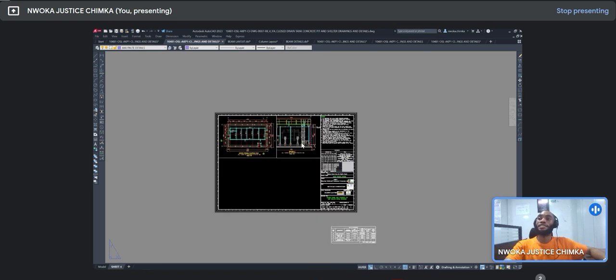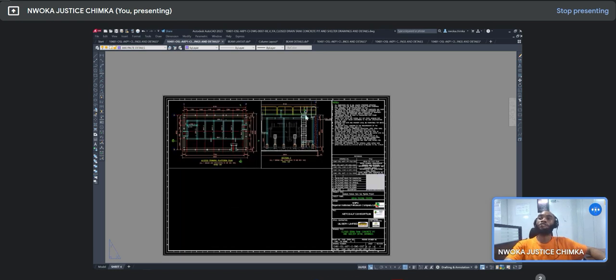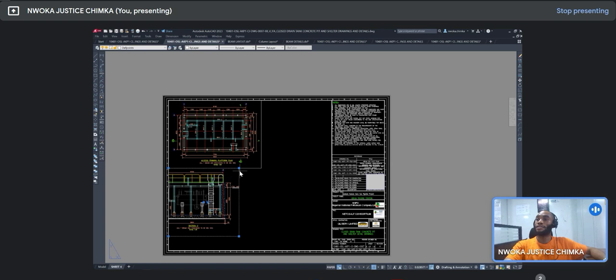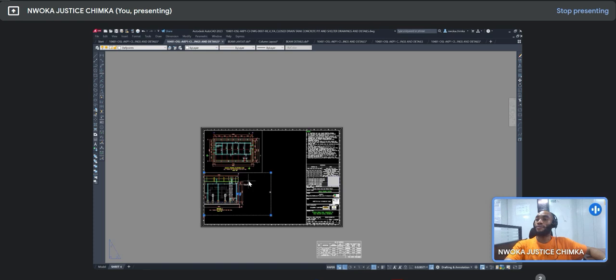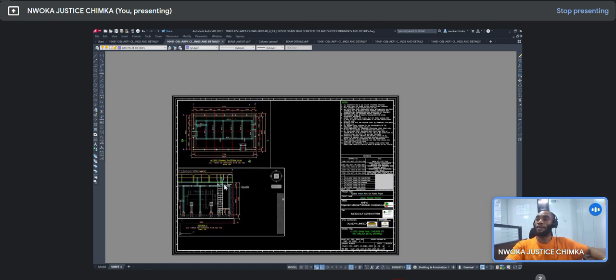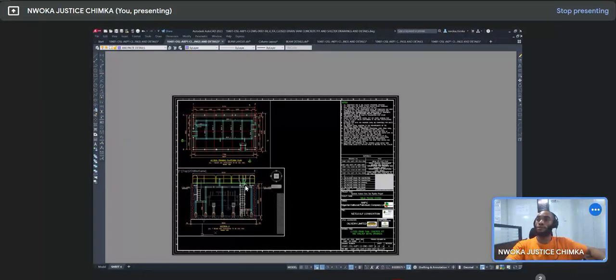Okay, so you can now see that this drawing is not entering into this space here. I'll have to bring this drawing now backward. Just move it down and then try to enlarge it for it to fit in. So I'll put it on this area here and then enlarge this my viewport space here. I'll just turn on my F8 to make lines straight, and then keep this here, and then I'll now double click here to palm my drawing inward, like into this place.